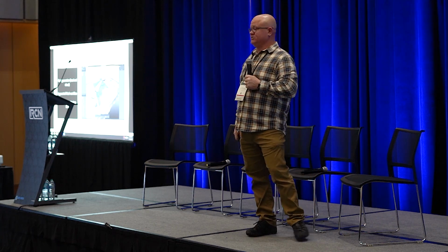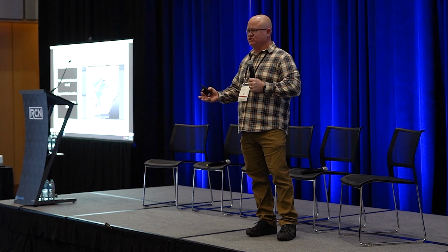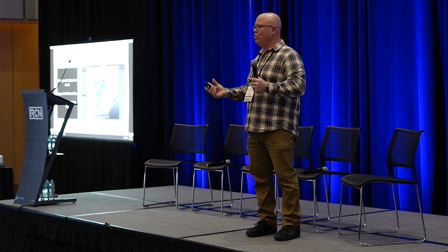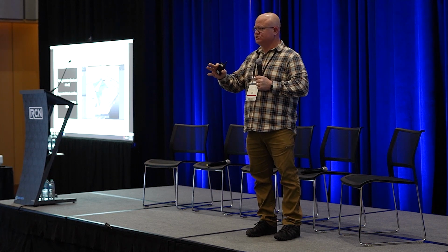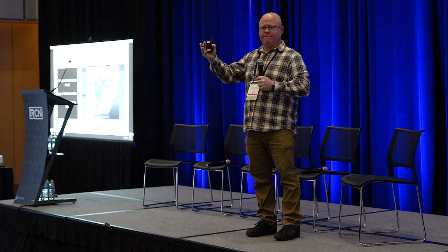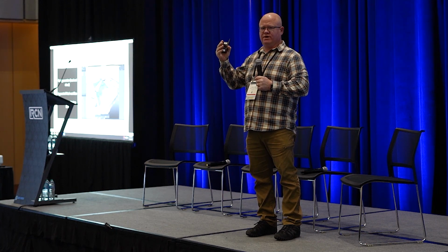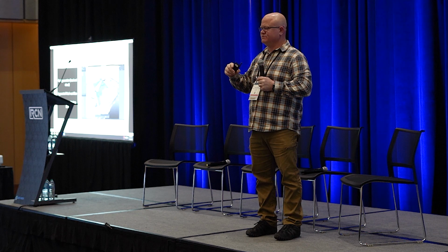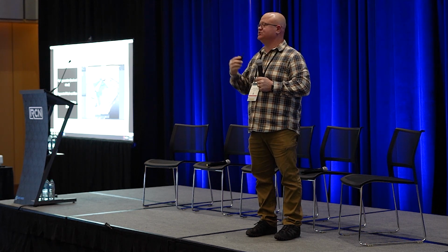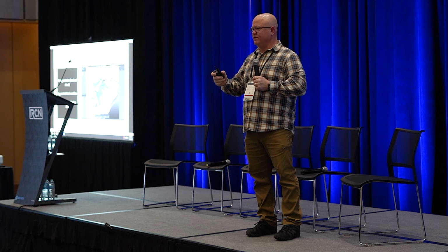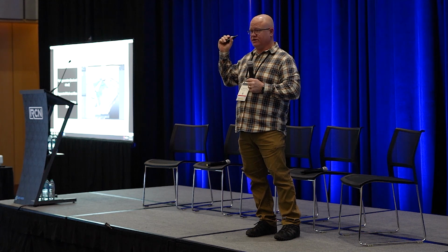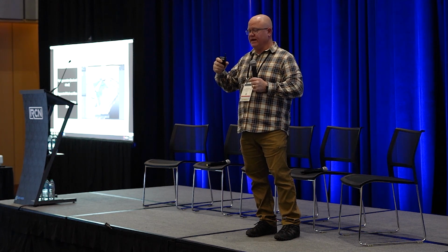Now, once it was on my machine, then I can go into what's called the mesh editor, and I can start to classify things just by selection. I can select something, put it in a specific classification. I can turn the whole mesh off, grab just that one classification, and export it out. I can export it out into, it used to be a PFX file, but they changed the format in the last version, so it's not that anymore, but it's a file that comes into Revit. I can export that out in that file format, or I can export it out in a Navisworks format so that I can do clash detection in AEC Pro or model coordination.